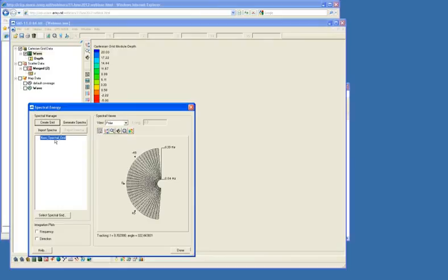So once that's created, you can do one of two things. If you have the bulk criteria, which is the wave height, period, and direction, you can create a spectral energy from those discrete values, or you can actually take information from a wave gauge that may be a CDIP buoy or a NDBC buoy, some information like that.